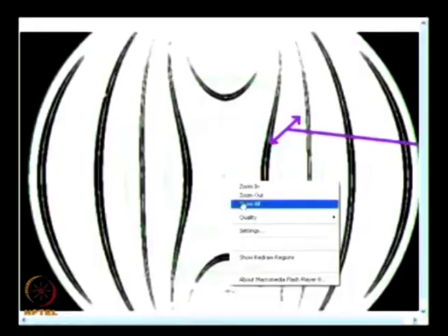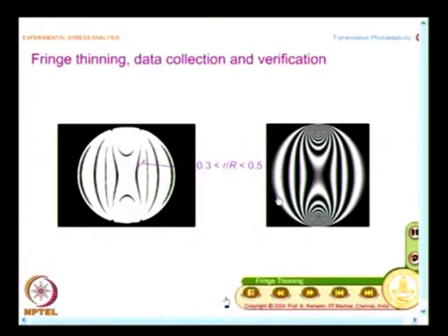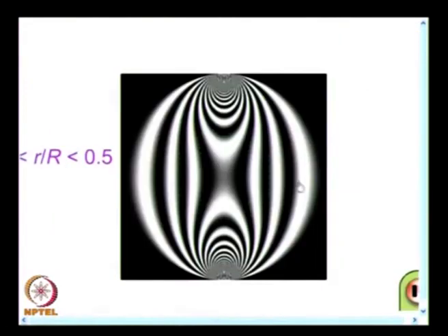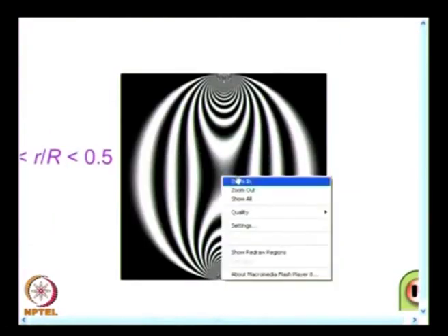The choice of data points also matters, and what is shown here is I have the fringes reconstructed, because we know the stress field in a circular disc. Using the theoretical information, it is possible for me to reconstruct, and this is to illustrate, if you do only one least square analysis, your choice of data points matters.